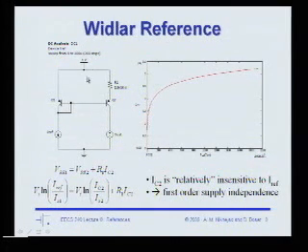It's developed by taking a delta VBE, the difference between these two transistors' VBE, across this resistor. And since delta VBE is relatively small, even a 10x difference in current only gives us about 60 millivolts, this current is also going to be very small. So that's one application of this circuit: to generate very small currents.